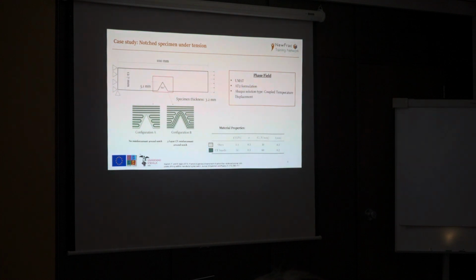As far as material properties are concerned, both for the Young modulus, for the Onyx and the carbon fiber bundle, the values were given by the producer of the 3D printer itself, which is Markforged. The L has been considered a numerical parameter, and we'll discuss later about the L itself, while the GC value of the Onyx has been given by literature,